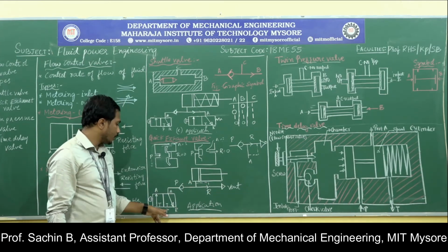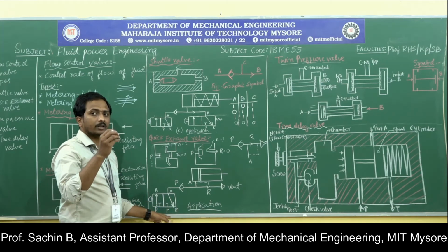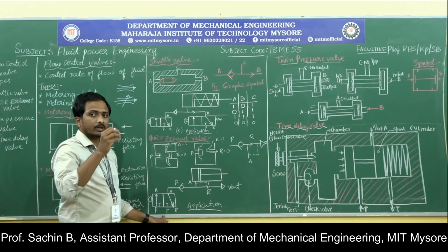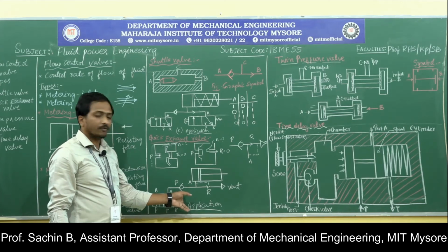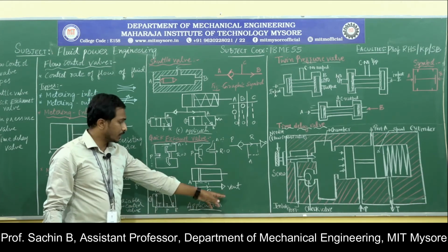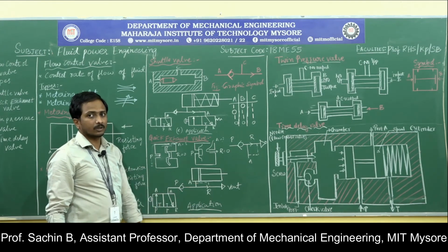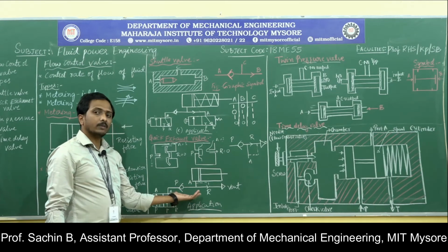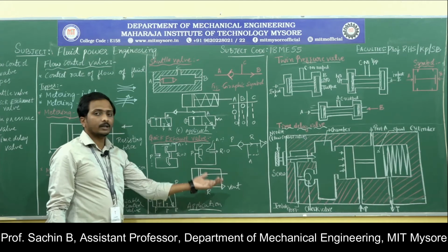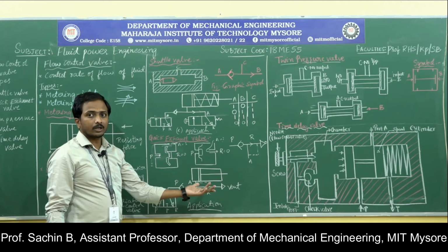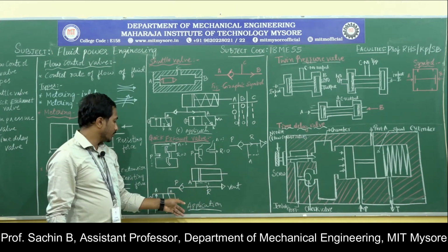But here with the help of one kind of valve, quick return is possible. Quick return means the air that is supplied inside the cylinder should be released with the help of the quick return type of valves by allowing that air to the atmosphere. We are releasing it directly to the atmosphere. Because when it comes to hydraulics, we return to the reservoir. When it comes to pneumatics, we directly release the compressed air to the atmosphere in a smooth manner. You can clearly observe here.